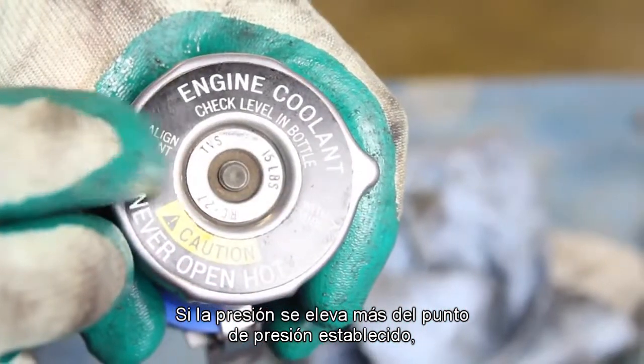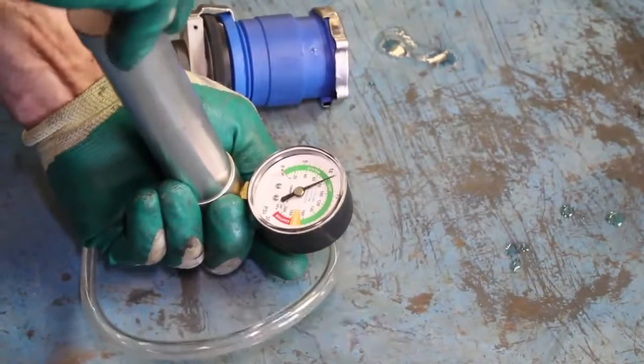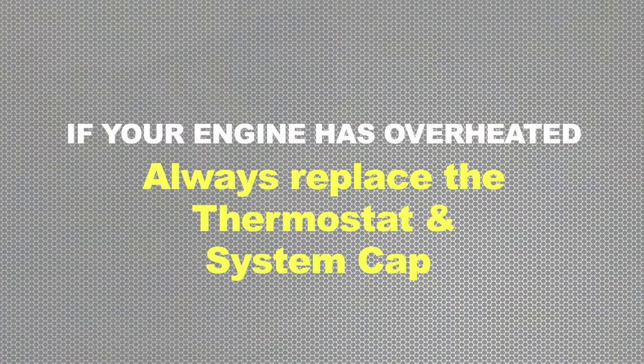If the pressure builds up higher than the set pressure point, a spring-loaded valve in the cap will release the pressure. The radiator cap can be tested with a kit available at your local parts store. If an engine has overheated, the radiator cap and thermostat should be replaced.